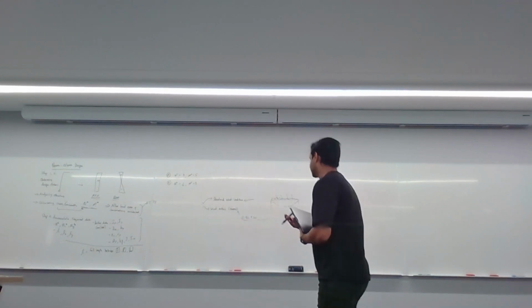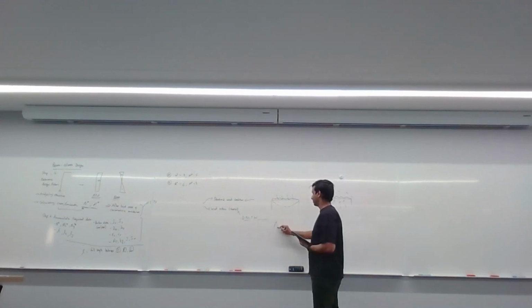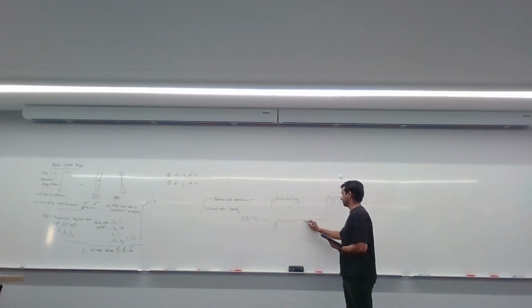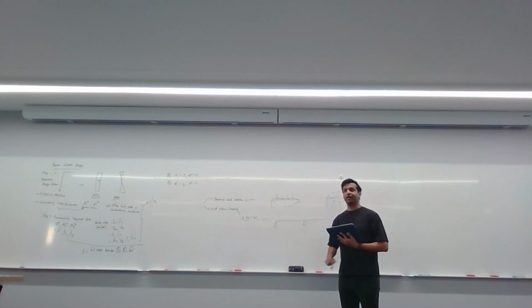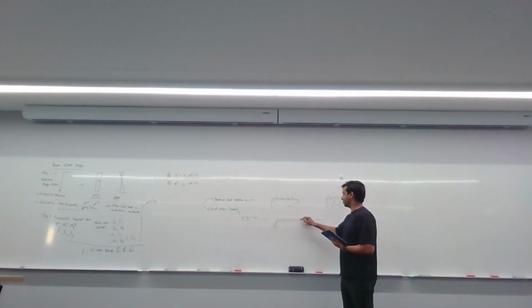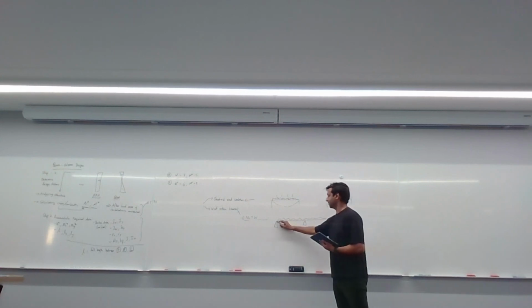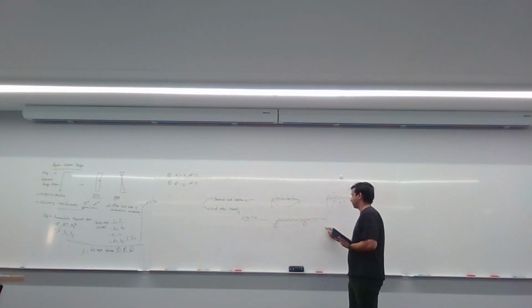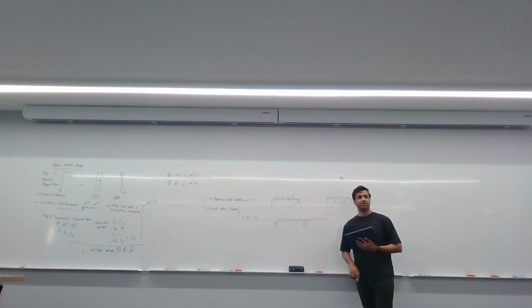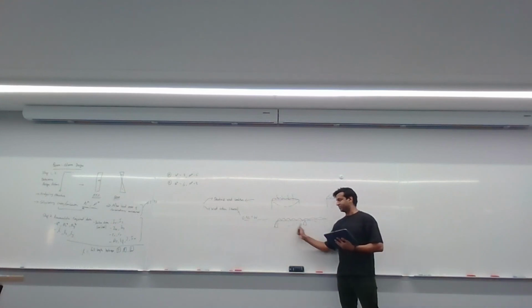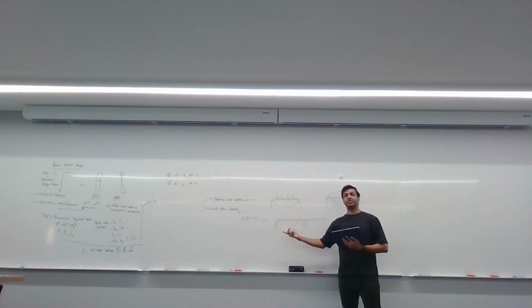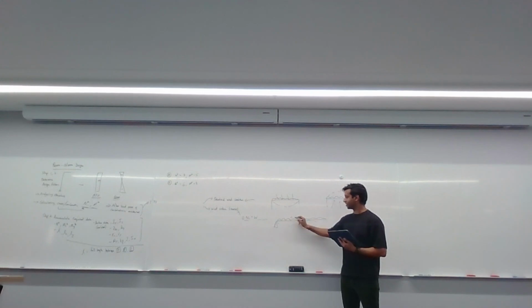Okay. So if I draw this out here, just quickly, what I'm really asking for is, that's your beam. You've got a UDL that's across this entire thing. What's the beam going to look like when it bends? It'll do something like that. That's what it looks like when it bends, okay? From this part to this part, in this segment, your compression flange is the top or the bottom flange? Top flange, okay. Compression is on the top flange.